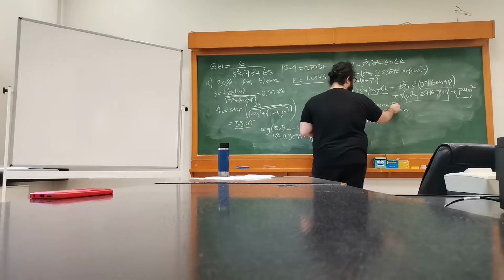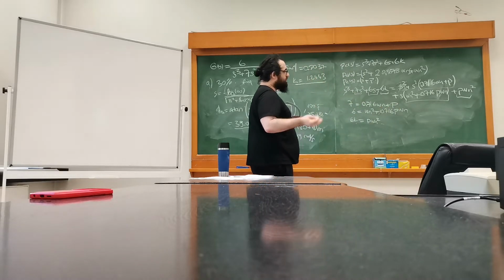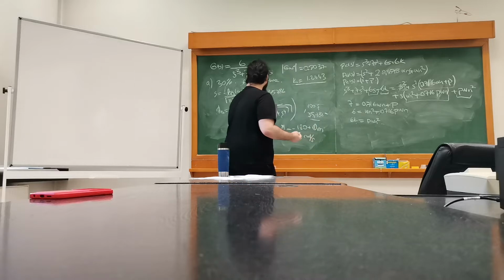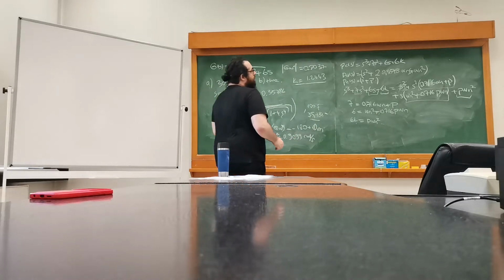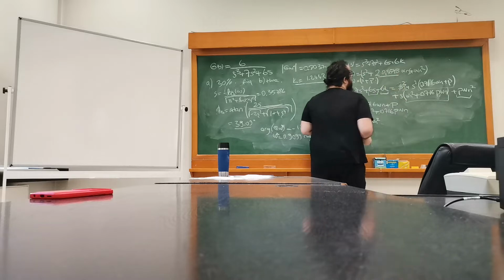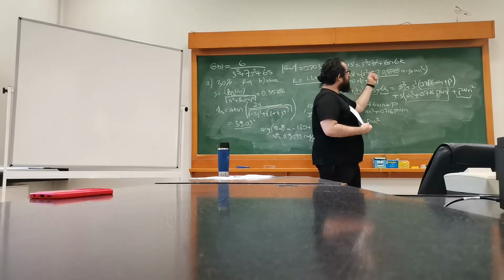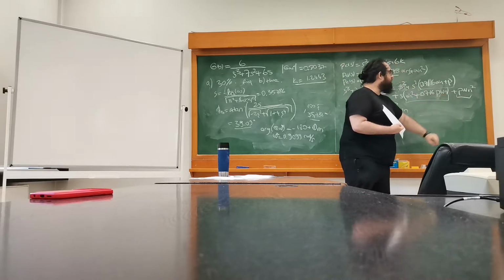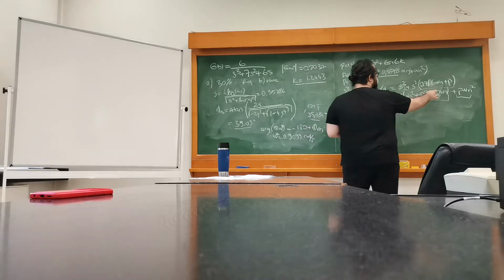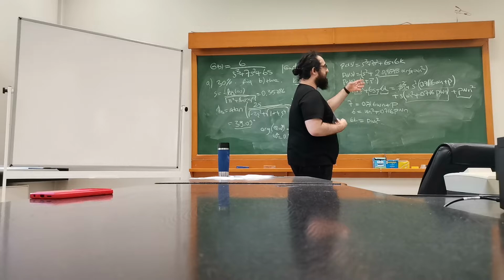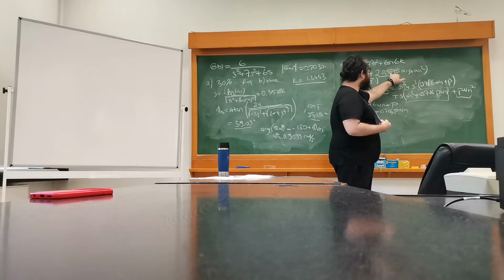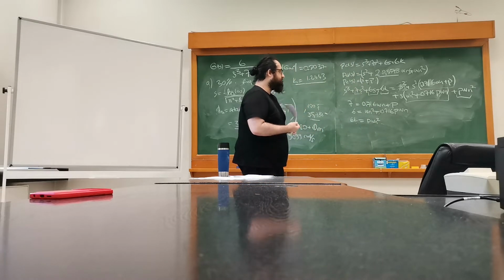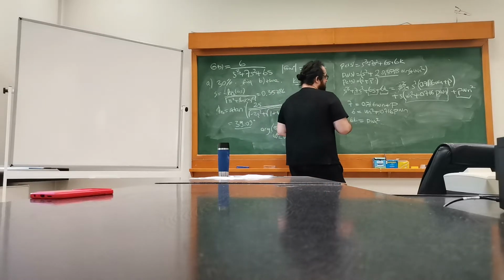Now we have omega n, p, and k, 3 unknowns, 3 equations, but these equations are a little bit painful. The basic fact is that since we have only overshoot, we only know this part here. And our desired polynomial has a squared term here. If you multiply them, you'll get omega n squared times p, which is highly nonlinear. We also have this multiplication here, which doesn't happen if you know what omega n is. Because if you know omega n and you don't know zeta, this is basically linear, and linear times linear is not really that big of a deal. But in this case, it's a bit harder.